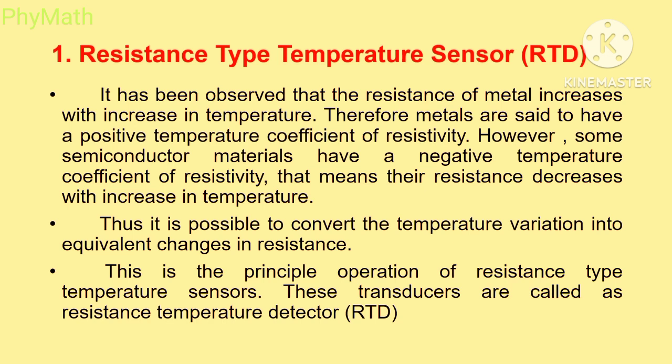It will be either PTC or NTC. If you are using metals, the resistance will increase if the temperature increases, and if you are using some semiconductor materials, the resistance will decrease with increase in temperature, that is negative temperature coefficient. This is the principle of operation of resistance type temperature sensors, and these transducers are also called resistance temperature detector or RTD.